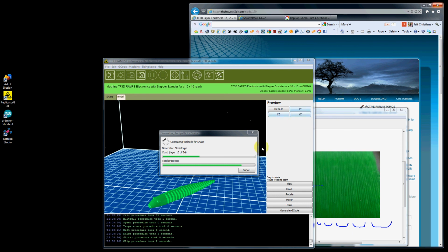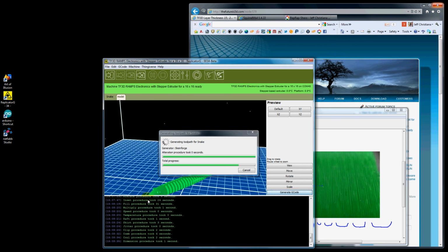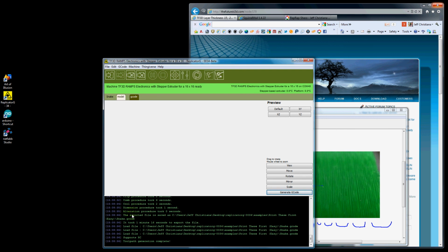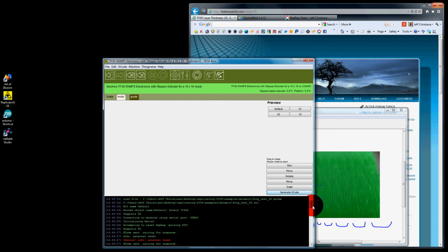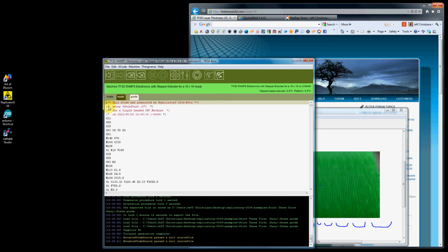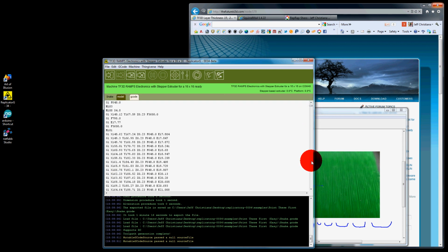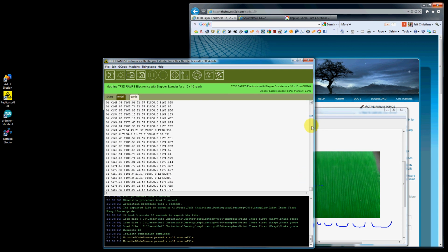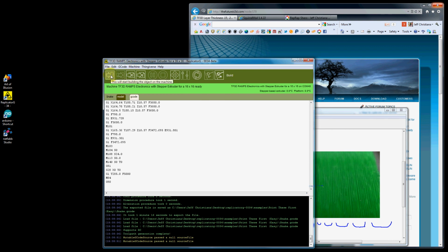Okay, the Gcode's about done. Down below in the status window, you're seeing that it's covering each section. It says it exported the file. Here's the location. It took 1 minute 16 seconds to generate the Gcode, and dual toolpath generation is complete. So here you have successfully created Gcode for a 0.45 layer for a 16 by 16 printer. If you take a look at the Gcode, you've got your start, and I'm sure you've got your end. Scroll down to the end, and you are ready to print. Click the print and click the build button, and away you go. We'll see you in the next video.